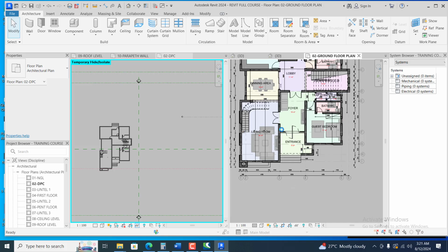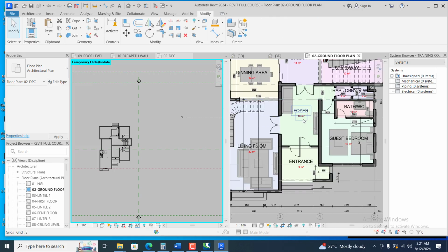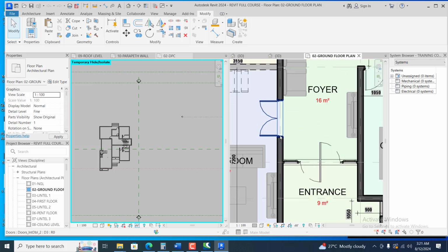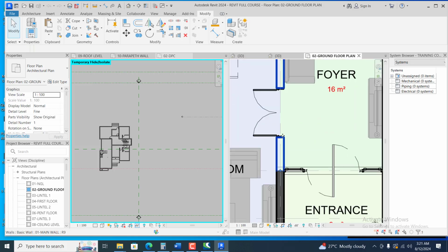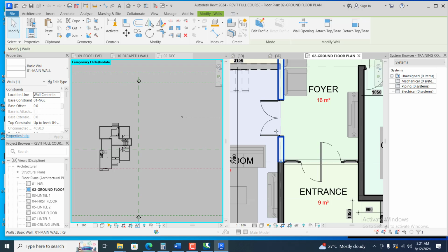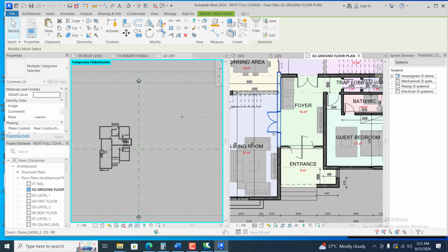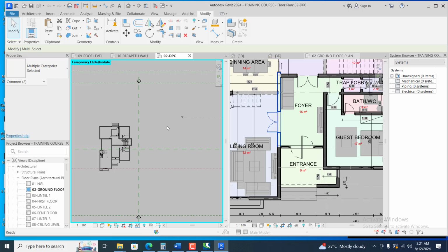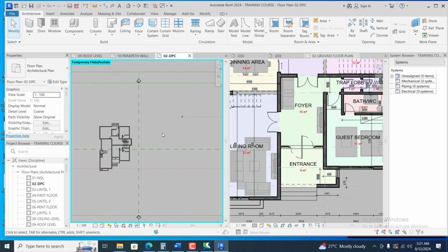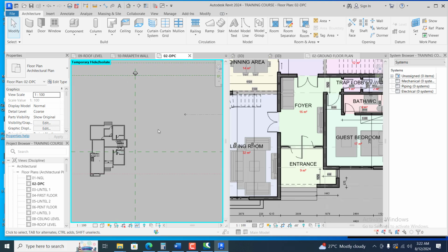click here to switch to this model. These are two different models, mind you. They are not the same, in two different interfaces. Now by clicking on this wall, I can just copy it with the walls, because you cannot have a door or a window without a wall. So that is why I'm copying everything with the wall.